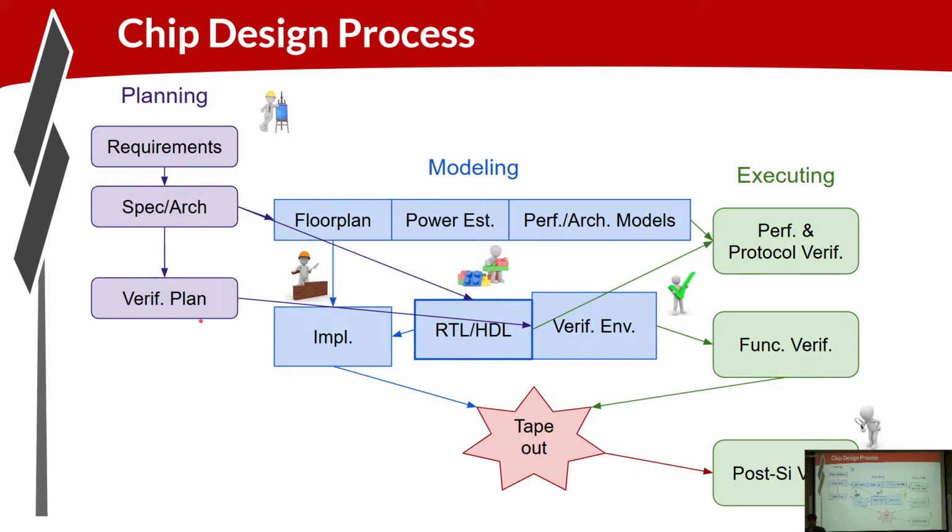So again, essentially once you've checked off all of the items that you defined in the verification plan, and the verification team says, okay, we believe this is 99.9% likely to succeed, or whatever your confidence targets are, you go ahead and tape out the chip, which means you provide the data that goes off to fabrication and becomes the silicon, and the silicon comes back, and you start the post-silicon work.